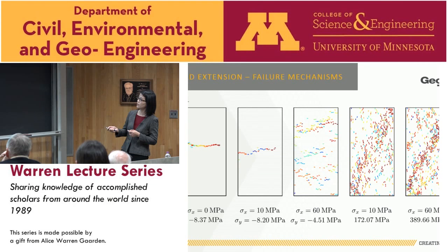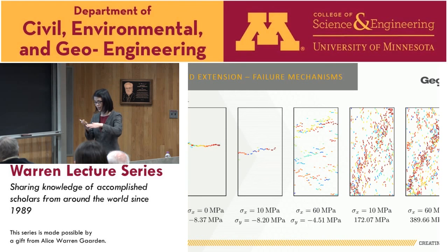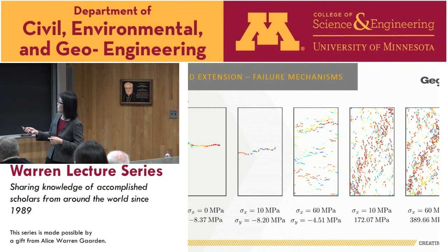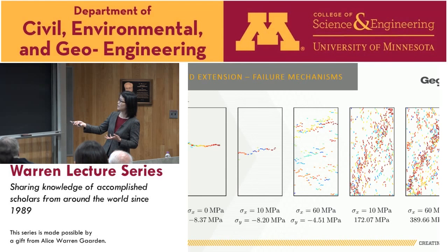When you have compressive stress on the side, these seed cracks start to develop parallel to sigma 1, but they are scattered. Then those become linked, forming step-like features. For example, here, here, here, and then they get linked, becoming a step going up and a step. That seems to provide a mechanism for the transition from a mode 1 crack to a shear band. These two, because of the way the simulation is set up, you need to flip them 90 degrees to compare these two with the other three.